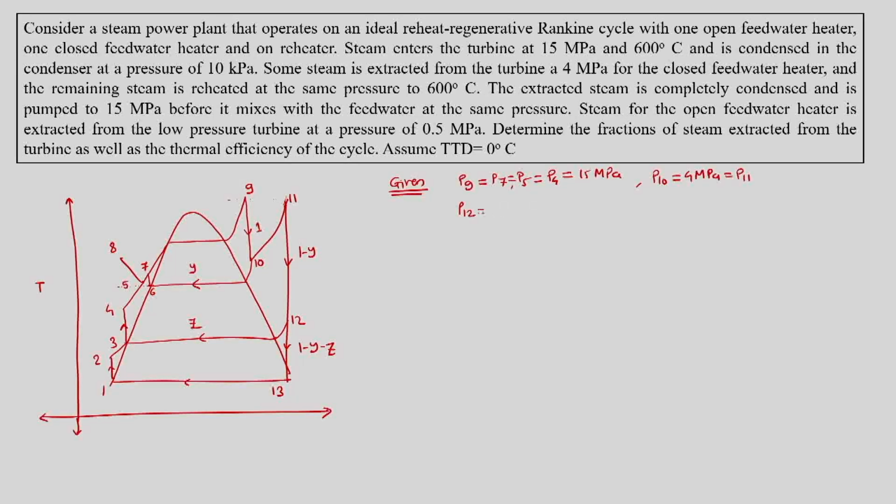But P12 is 0.5 megapascal, and that is equal to P3, and that is equal to P2, and similarly P1 is equal to P13, which is equal to 10 kPa. So, here we are having 15 megapascal, here 4 megapascal, here 0.5 megapascal, here it is 10 kPa.